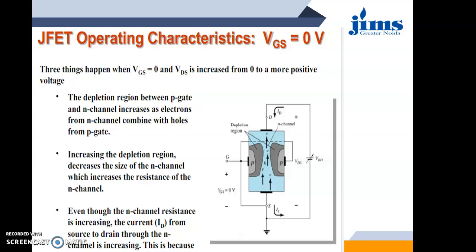This is again the concept that the source should be forward biased and the drain should be reverse biased in order to operate in the active region. Because of that, the charges will move from the source region and will be collected at the drain region. Along with that, a special shape of depletion layer is formed across both PN junctions, which is called wedge shape.